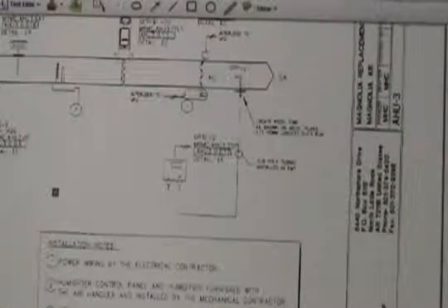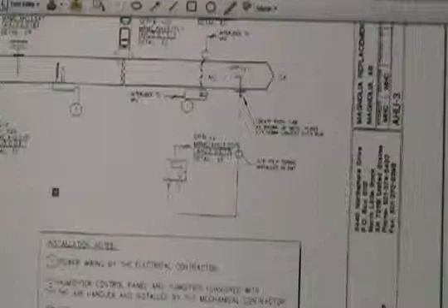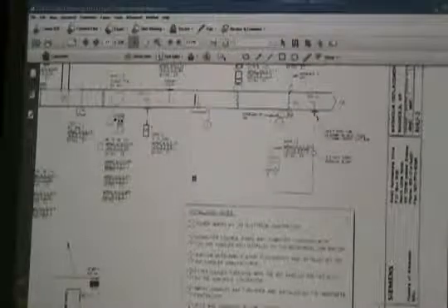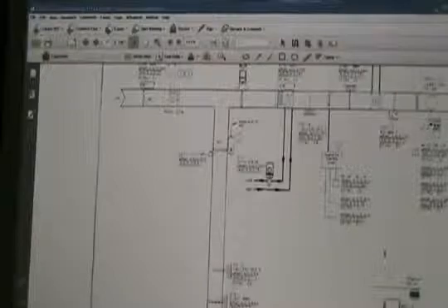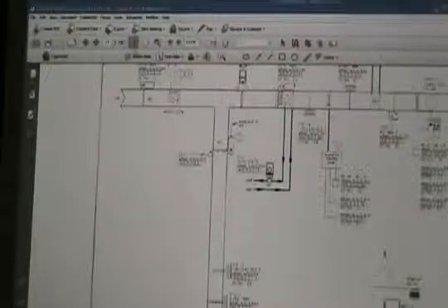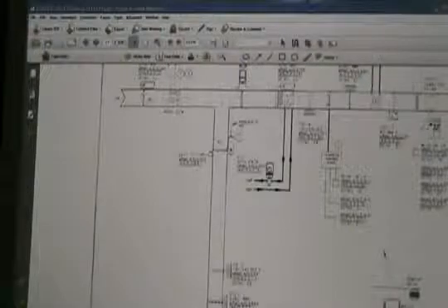We're not showing a building, but it would be a differential pressure setup very similar to this right here that's common for the whole building. Probably on one of the first 4 lobbies, entrance lobbies. And again, that's just an input into our system. We're monitoring that pressure. So if the building starts to go negative, probably on both the air handling units 1 and 2, or 2 and 3, we would start opening that damper to maintain pressure.